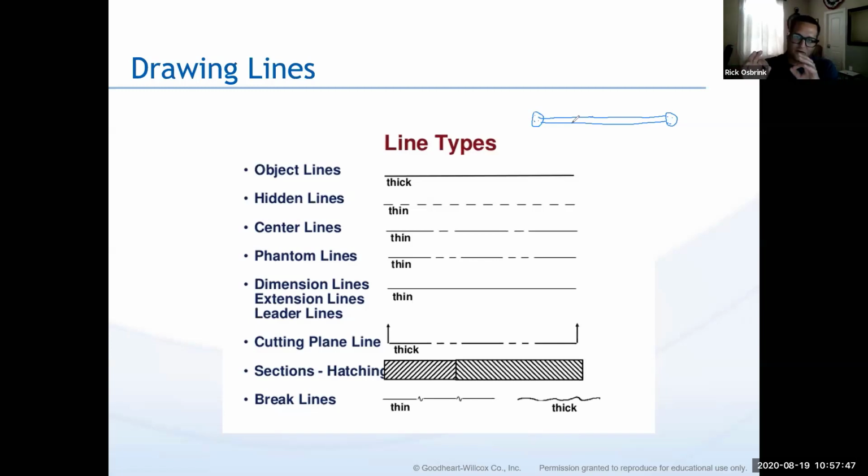And when it gets scaled really, really small, then it's hard for me to show you the detail and stuff that's happening over here. So I can do a couple things. I can show you either a cut section, or maybe I can just show you a view of just this area right here. Or what I can do is add in what's called a line break. And basically what a line break does is tell us that it doesn't change, okay? So nothing changes in between these two line break sections.